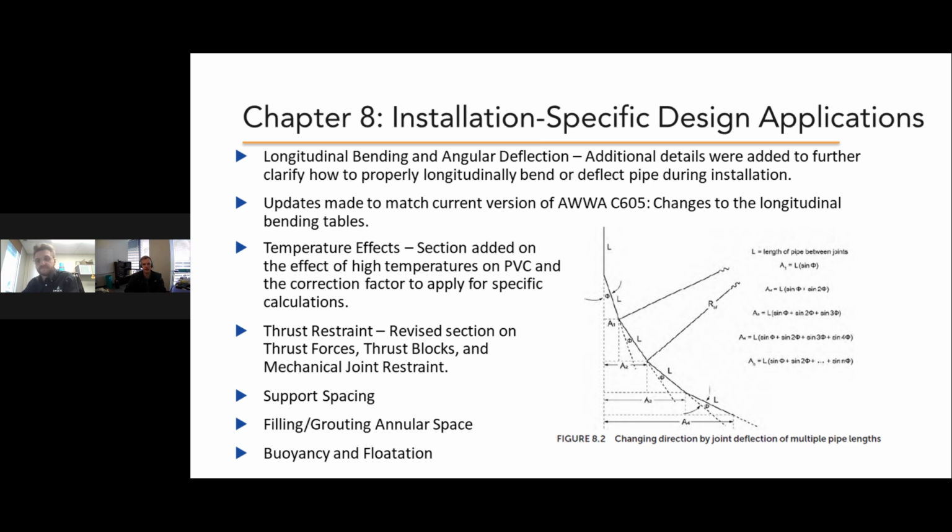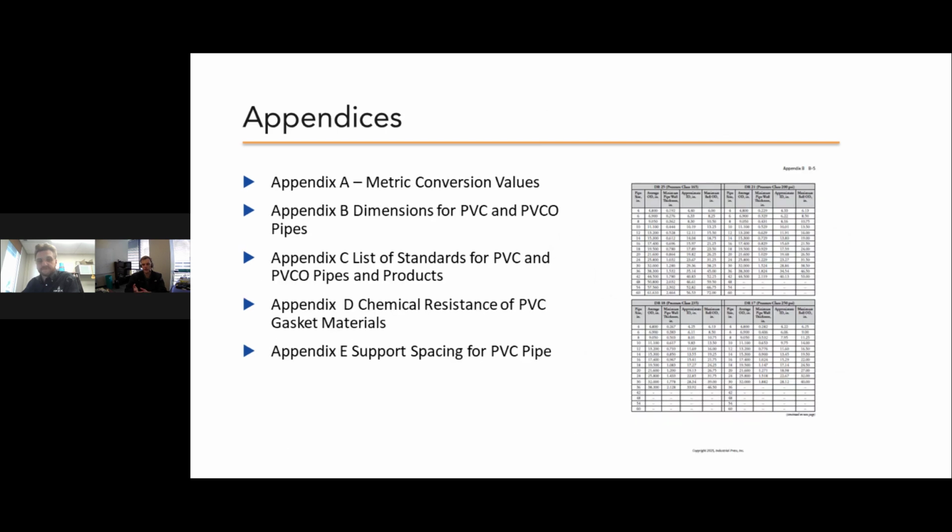And again, we do have those chemical resistant tables for gaskets. These are generally pulled directly from the gasket manufacturers, and they get into the different chemicals and the potential contaminants that will affect different gasket materials in different ways. So nitrile, for example, is going to be the most resistant to hydrocarbons. SBR and other materials might not be as resistant to hydrocarbons, but might be more resistant to certain other chemicals,